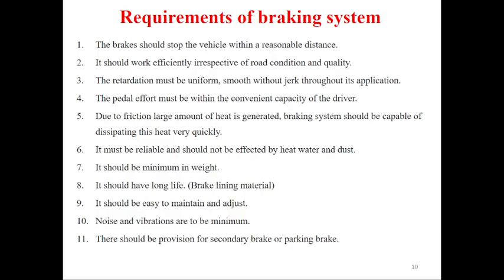Retardations must be uniform and smooth, without jerk throughout its application. The pedal efforts must be within the convenient capacity of the drivers. Due to friction, a large amount of heat at the wheel is generated, so the braking system should be capable of dissipating this heat very quickly. It must be reliable and should not be affected by heat, water and dust.